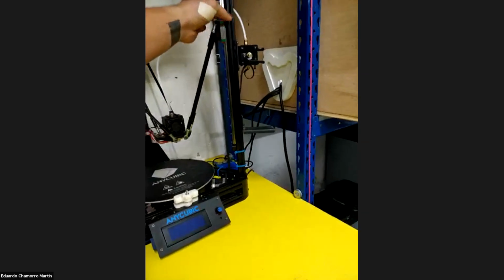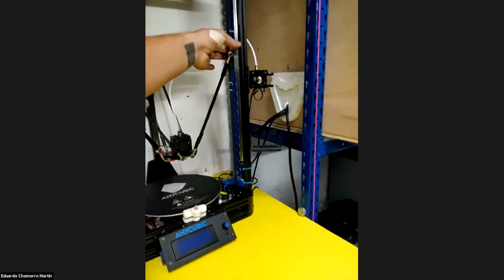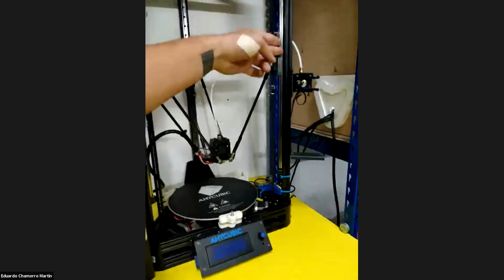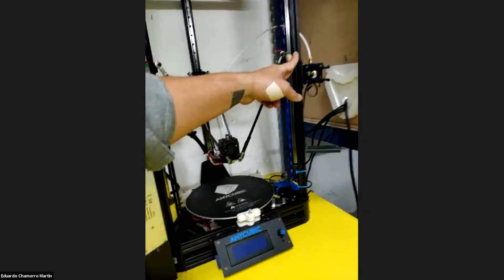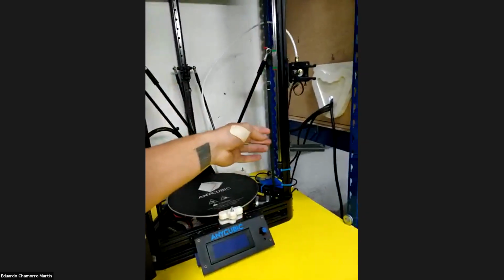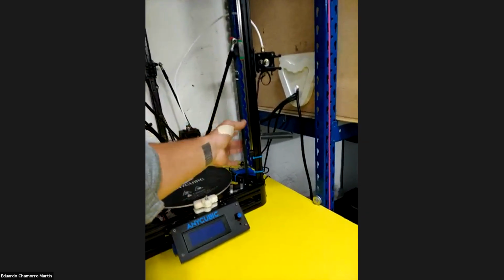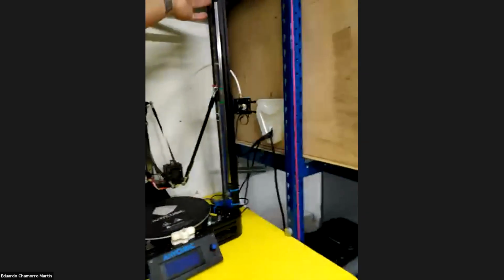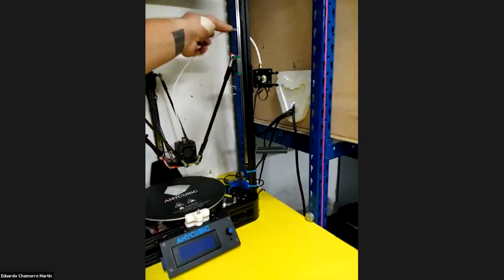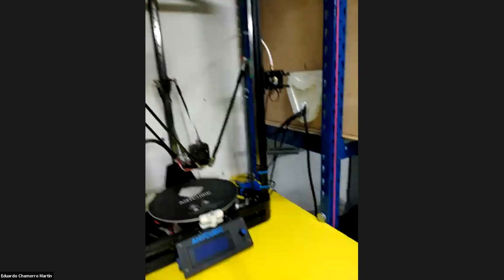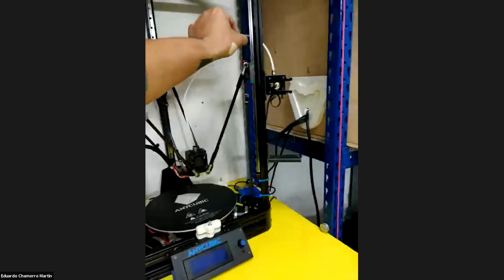And actually, this is what you usually want to go for. What happens? These guys are usually way more expensive, the linear rails with linear bearings. As we want to move fast and we don't have a lot of mass, we can go with belts. Actually, this is a really long belt distance. In this case, it might not hurt to go to a slightly wider belt, but just to keep the cost down, they have a thin belt.